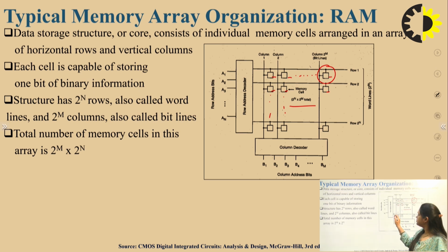We know the concept of decoder. In a decoder, if there are n inputs, then 2 to power n outputs are there. Like if 2 inputs are there, then the decoder is known as a 2 to 4 decoder. For n equals 2, it is a 2 to 4 decoder. Similarly, 3 to 8 decoder, and the same designing is there.